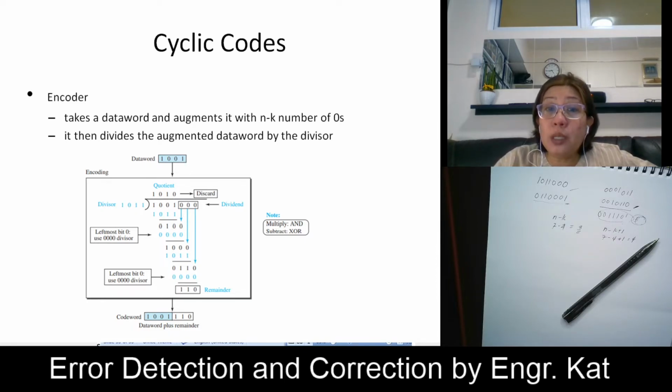Okay, so as you can see, there are no more additional bits here. The remaining number of bits is already equal to 3. So therefore, we have to stop there. The 3-bit remainder forms the check bits R2, R1, and R0.